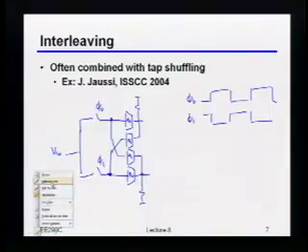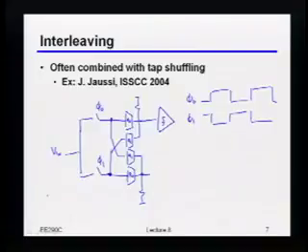Not necessarily. So if you did something like this, what you'd typically do is your data receivers would basically be also deinterleaved. So let's say this would be phi 0, and let's say it would be phi 1, something like that. You could indeed reserialize it if you wanted to, but if you've already gone through the pain of generating all the clocks and stuff, you probably will end up doing something like this. We'll talk actually a little bit more about this.